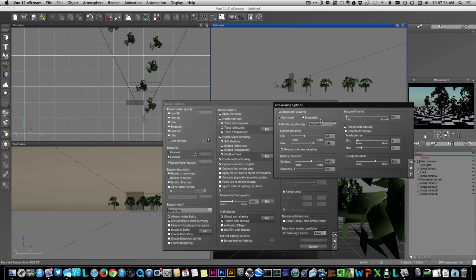Now you're going to wonder, why would you want to do that? Well, because if you fire a ray, let's say you had a checkerboard that was miles away, you fire a ray into it, you've got a 50-50 chance of hitting a black or a white pixel. What happens if you only keep hitting the black pixels and you keep missing the white pixels because of your resolution? The image is going to look black. So you start firing more and more rays into it. Eventually it's going to go, I'm hitting black, I'm hitting white, I'm hitting black, and you'll actually get a grey look, which is true. If you look at a black and white grid like this from a long way away, it's going to appear to be grey. So that's why you need to fire more sub-rays per pixel.